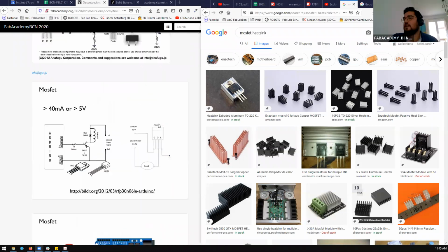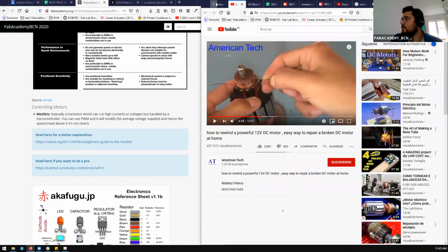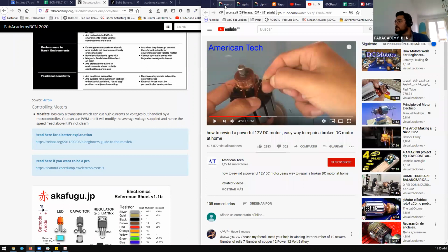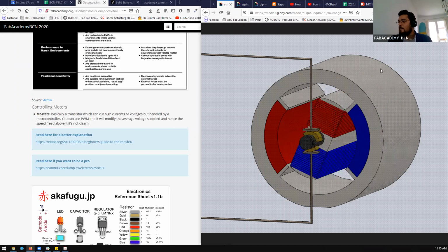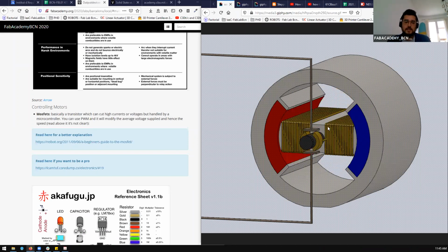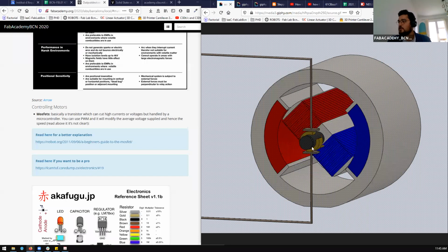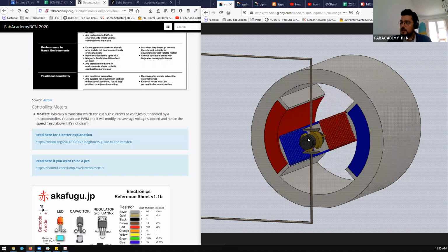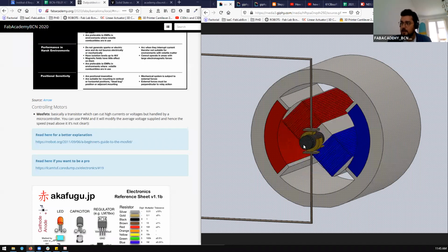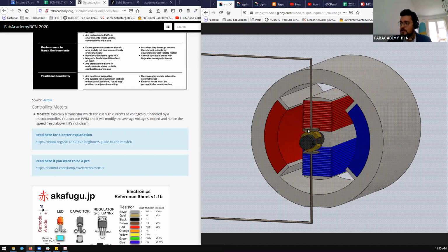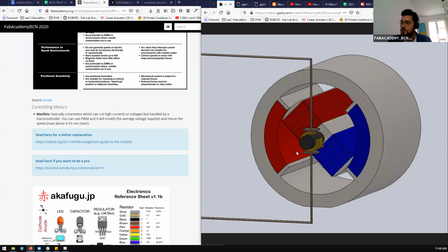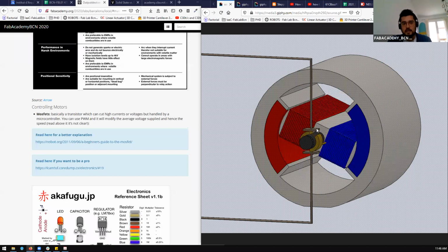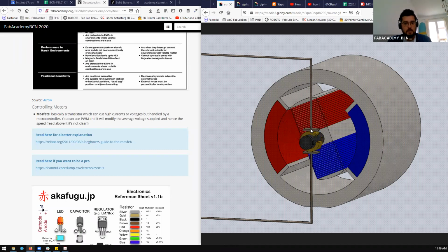Okay, just a few things more on the motors, because we have seen the theory about it with Óscar. How that physically applies, how we change the current, for example, for a DC motor. You see on the pads, the cables, these are some semi-cylinders, and by cutting in half, this plate is connected to positive and this plate is connected to negative. So when the motor rotates, by its physical location of the copper, it automatically changes from positive to negative.